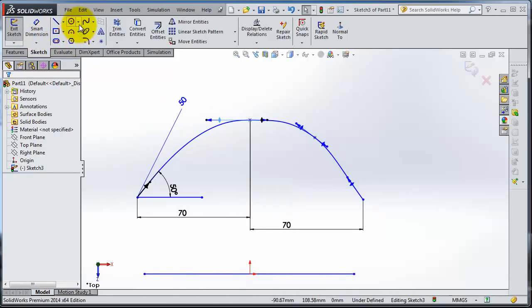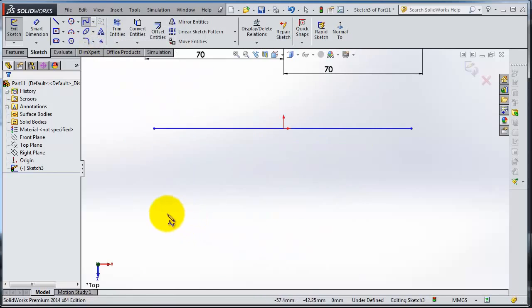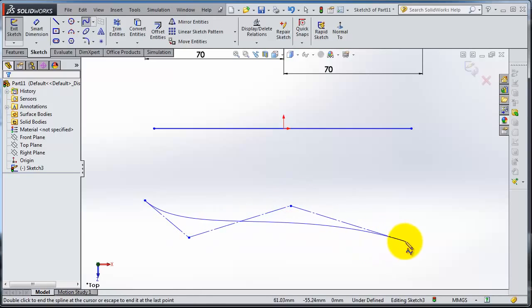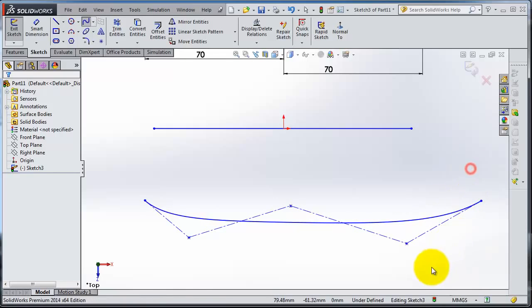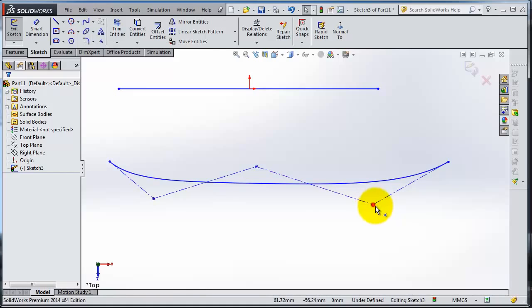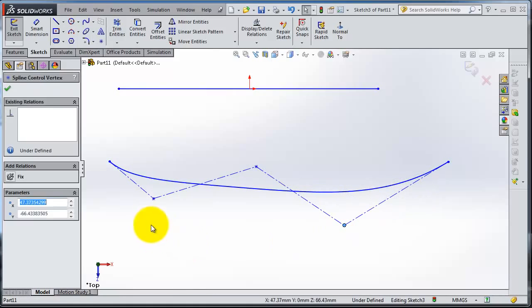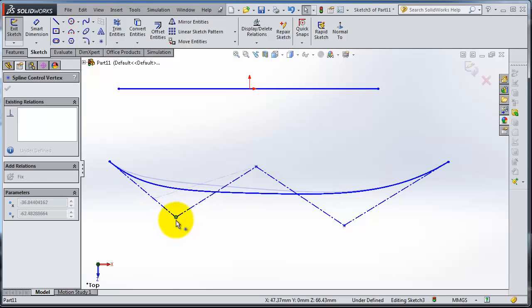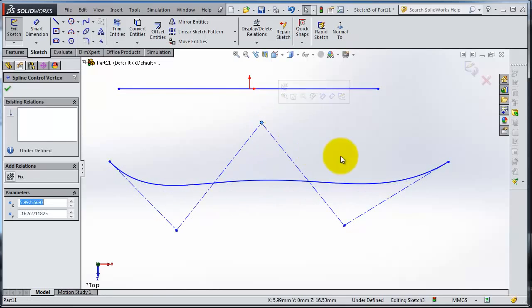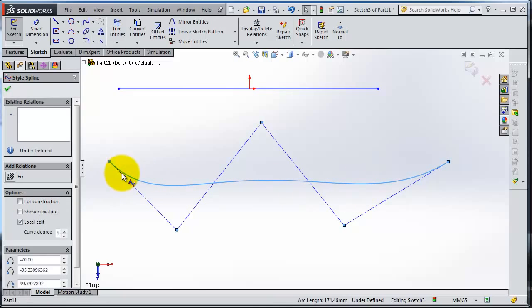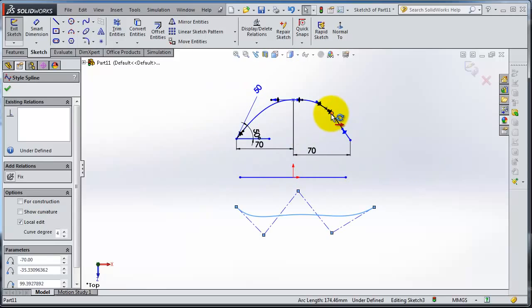And now you have the second type of spline, with guiding lines as a way for more control over your spline. You notice your spline is contained inside these guiding edges or lines. If you select that point, from that point you are able to control your spline. As you notice, you don't have the handle and the size as shown in the previous type of spline.